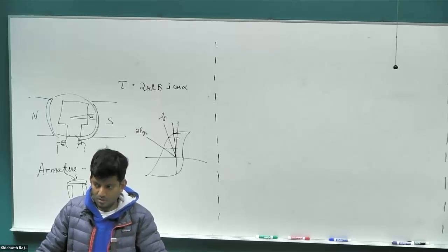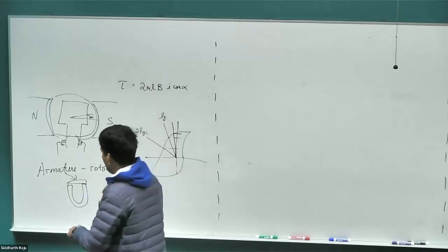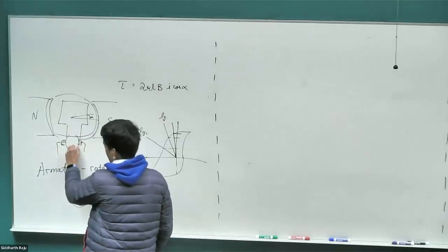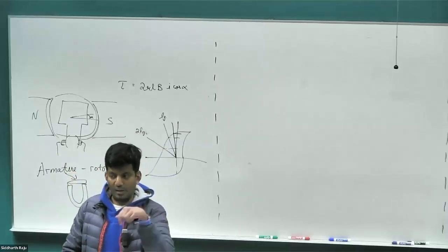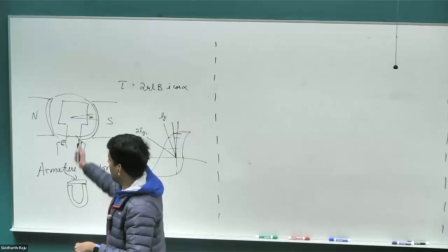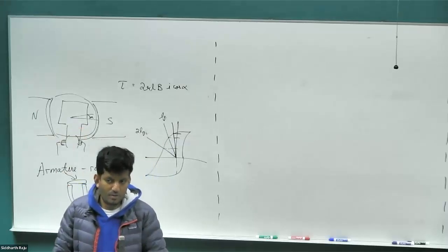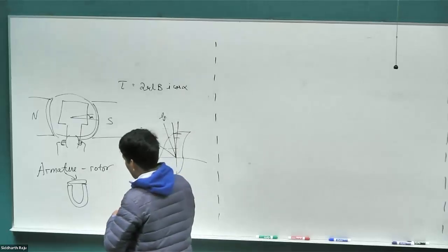But in some motors, the magnets will rotate, correct? That'll be in the AC motor, not in the DC motor. In a DC motor, we keep these fixed because we have this mechanism for the current to commutate. When we go to AC motors, we can do the same commutation by putting AC currents, so we can move these windings to the stator and put the rotor magnets on the rotor. Any questions? Okay, so that's the reason we want to put an iron core.